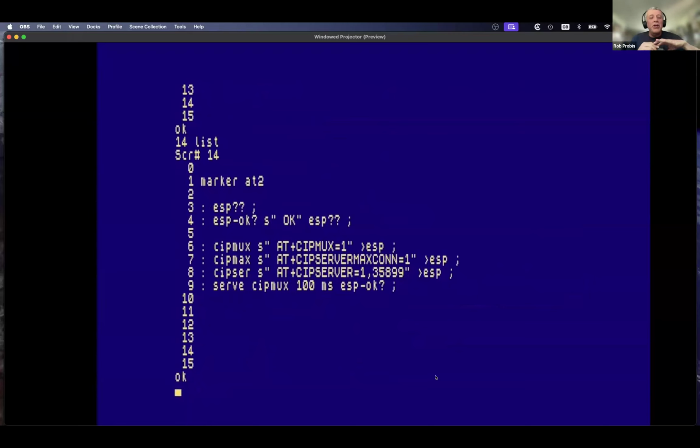And there's a couple of things you can do with these ESP01s. You can put it into transparent mode, which is a bit like the old Hayes modems, where when you did ATD, I remember from back in the early 90s, and then you put a phone number in, it would connect until you did +++. So there is a native mode, but there's also another mode where you're still in command mode, but it'll give you the text on independent lines for everything that's coming in, and there's a separate command to send stuff out, right?